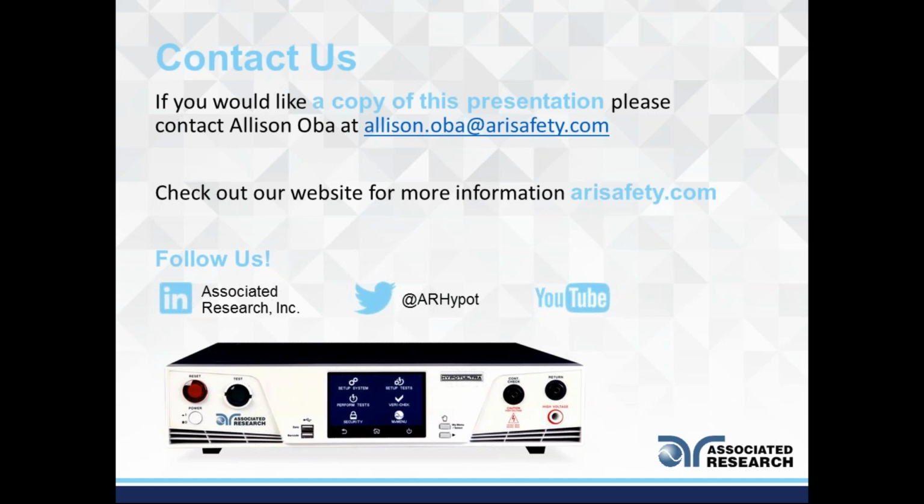So yearly is what we recommend, but from experience and dealing with different customers, we have seen some customers using a 6-monthly or even a 3-monthly quarterly calibration. It really depends on how the test environment is. If it's a very rough environment, you may lose calibration. Also, depending on the frequency of use, if it's very high frequency usage, you may want to check for calibration more often than once a year. So again, as a manufacturer, we recommend yearly, but depending on the nature of use and the condition the Hipot tester is being used in, you can definitely go for a 6-monthly calibration or even less. It's really up to the user in the end.